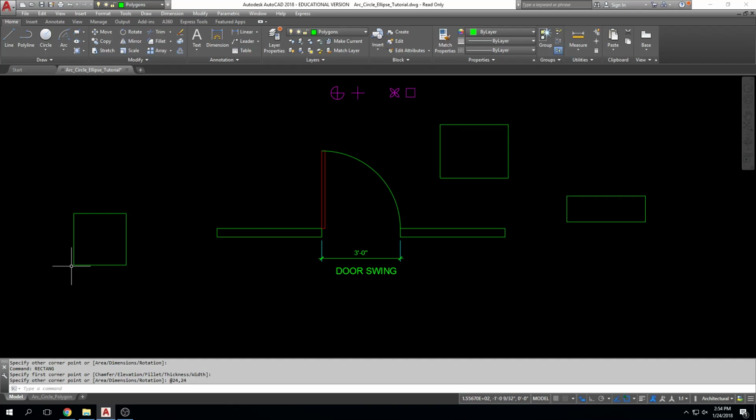And from that first point where I clicked, I have a 24-inch by 24-inch square that has been created, right? So that's one case of a relative input that we'll use in a drawing here. So that does the same thing as clicking on the dimension? Basically, yeah. The input is just different, right? Yeah. You're inputting an ordered pair instead of 24, enter, 24, enter. Yeah.